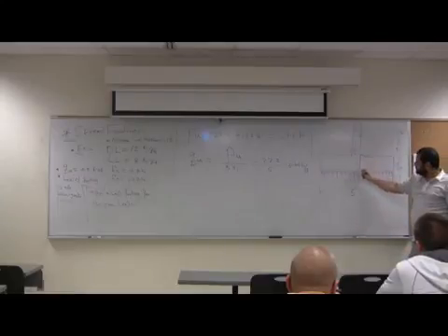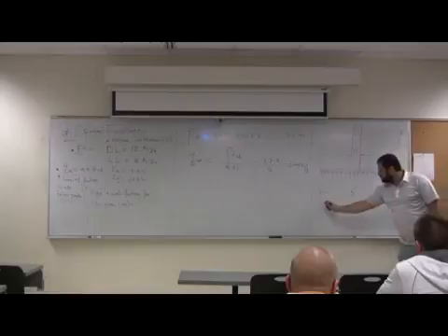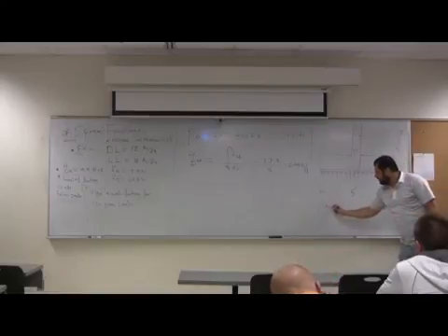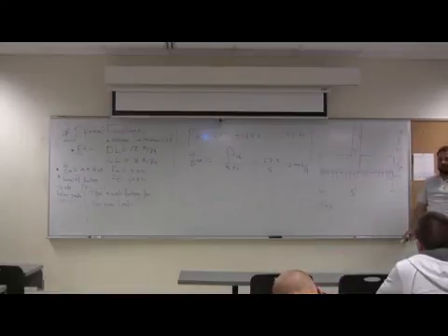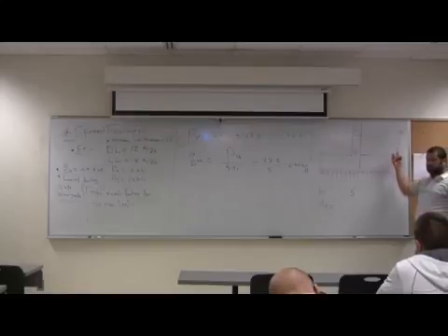So now you are looking for what? The moment, M ultimate, at the face of the wall equals what? Q ultimate times this length squared over 2.